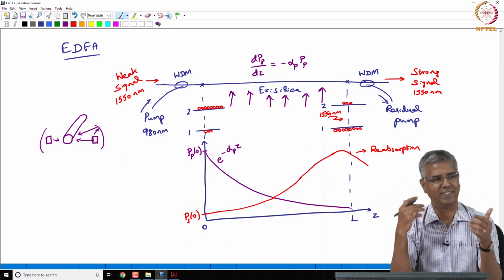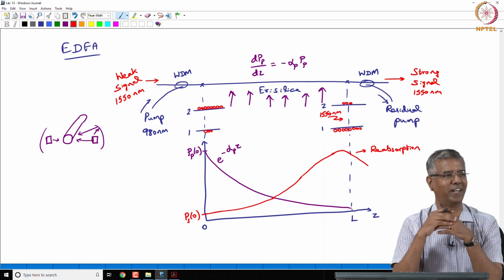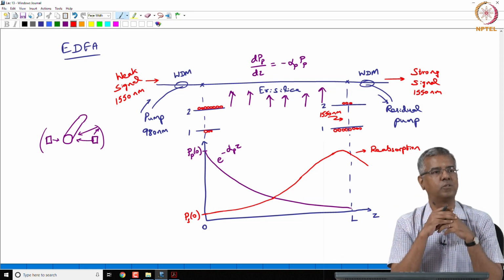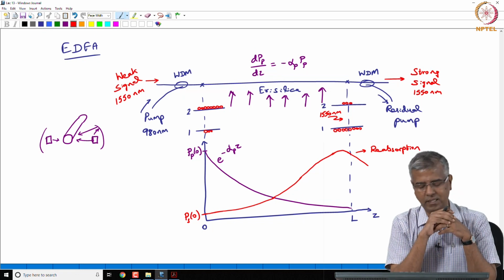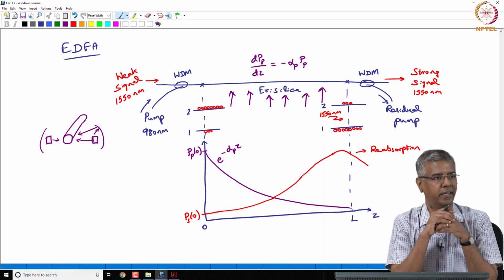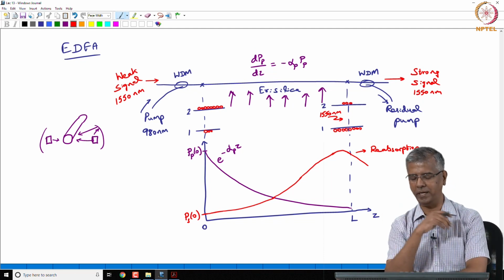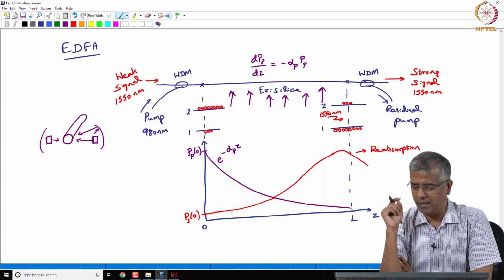So now we are starting to look at some advanced issues in advanced configurations. I'm glad you guys are thinking like this, but that's what you need to do to have uniform excitation, and that's a good way of making sure reabsorption is not happening. But the other point about counterdirectional pumping, let's examine that.